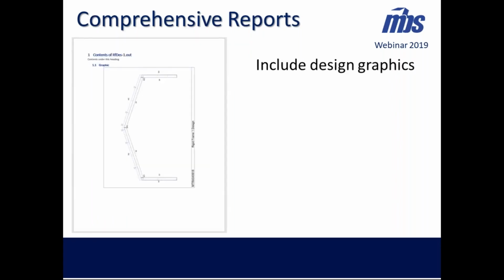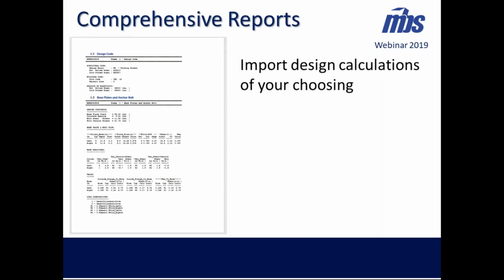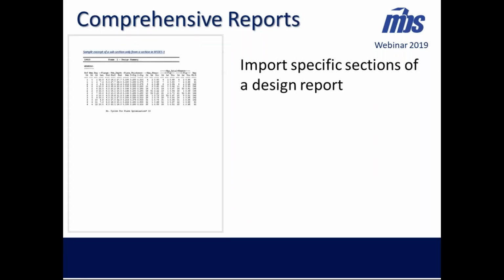It will import graphics such as your DXF, so you can pull in your design graphics as you like. It will pull in your design reports that are generated. And if you want, you can be specific enough just to pull in one section of a report. For example, in this one, I had it pull in the framing design, only the members subsection of the design summary of the rigid frame design. So you can limit it up and down as much as you want out of that file.